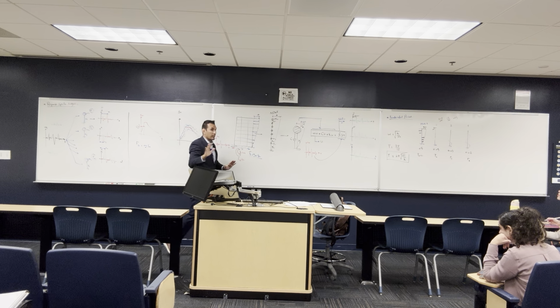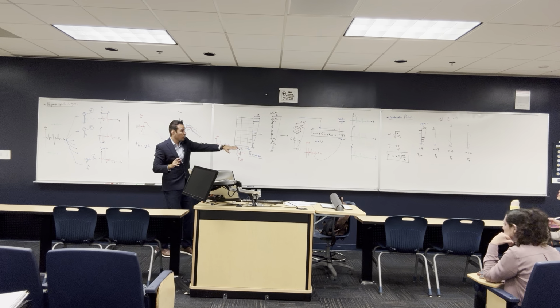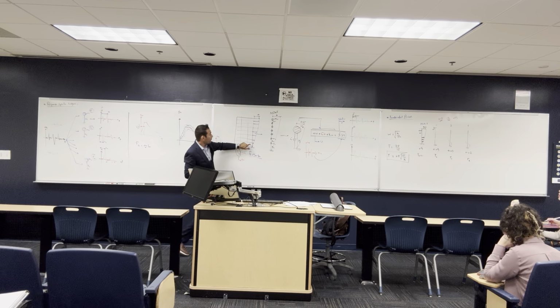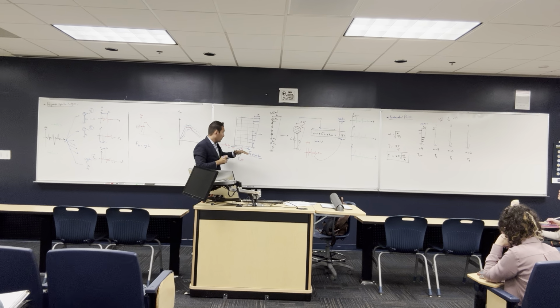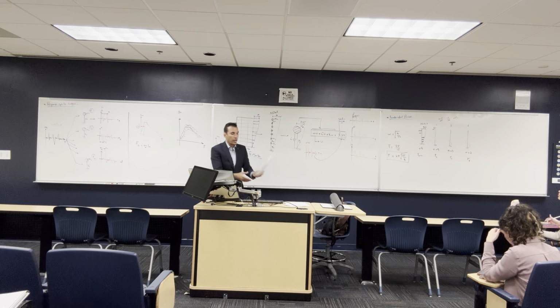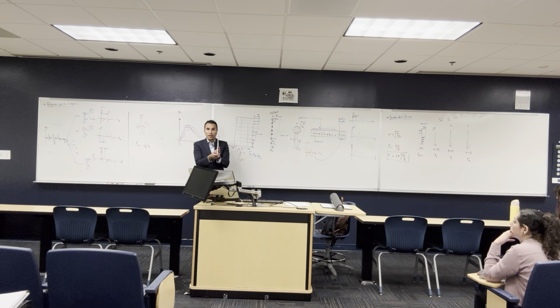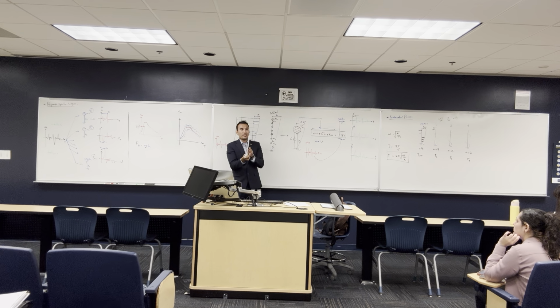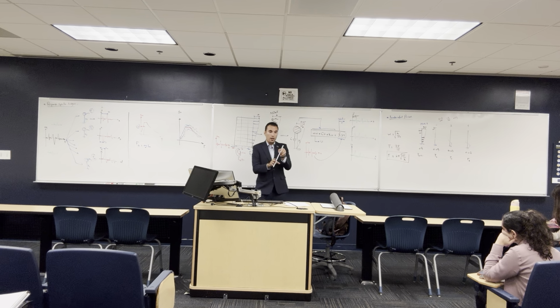So when we do analysis, as an engineer, I told you, we're only trying to find forces. Can you see all these three boards? I'm doing them to find the force that each story is gonna take from the earthquake. I wanna know the force at the base and the force at each story. So when I use structural analysis software and I have my building, I apply the force at each story and then run my model, and then my building is gonna move. Once I have these forces, the software is gonna tell me, you have this force here, it's gonna make a bending moment at the column here of like 5 ton meter, and the bending moment here is 2 ton meter. When you have a bending moment, as a designer, we put reinforcement so that it can resist the bending moment.